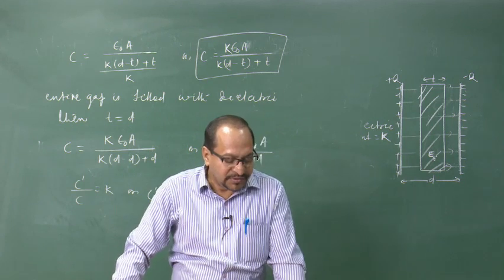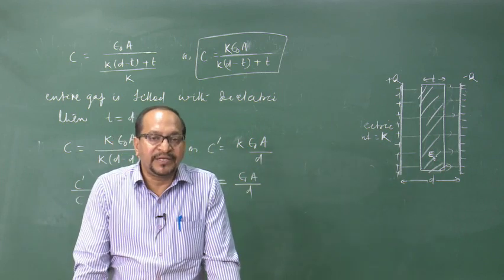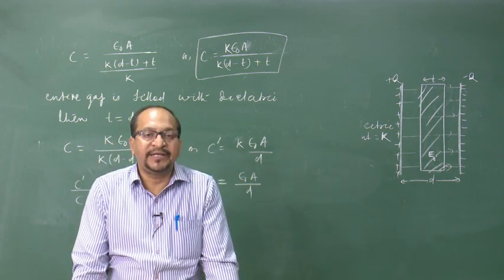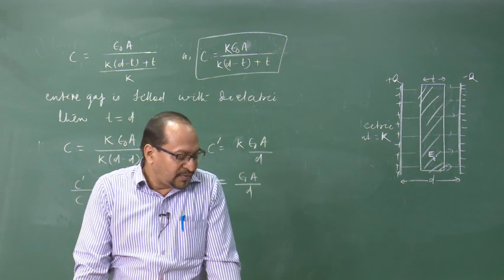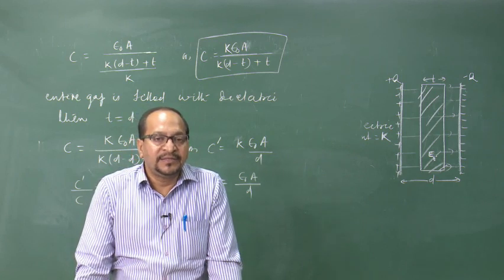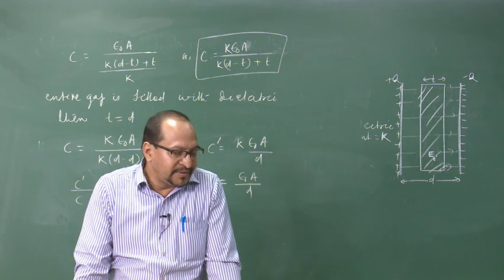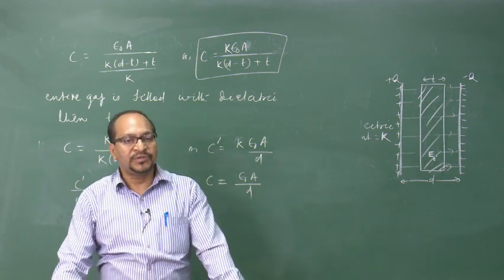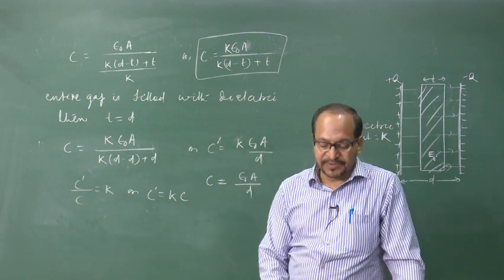Of course, there is a special kind of materials called ferroelectric materials which have very high dielectric constants. Ferroelectric materials often used in industry are barium titanate and lead zirconium titanate, popularly known as PZT. These are the materials we use in capacitors to increase their capacitance.